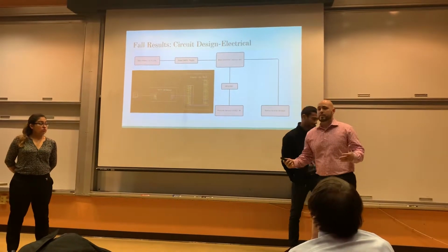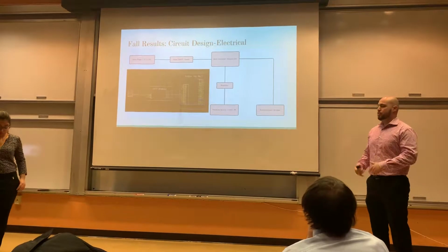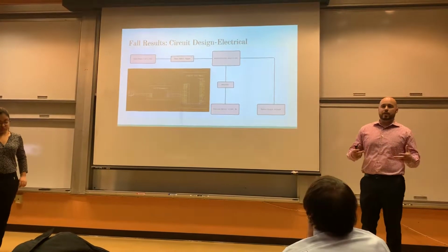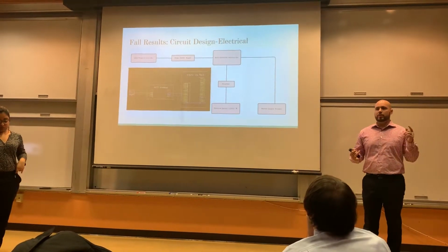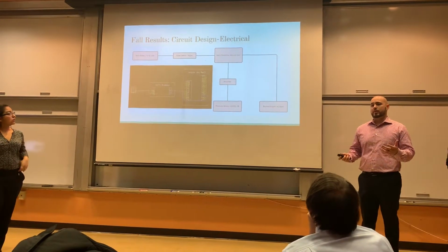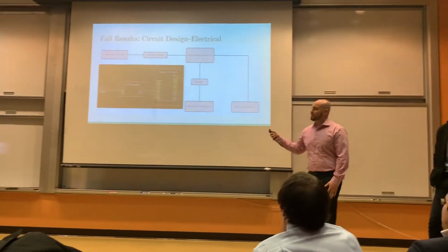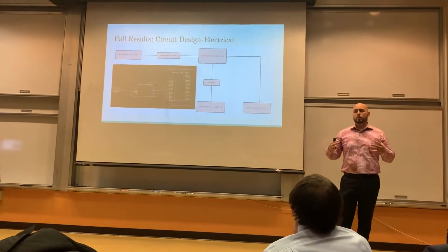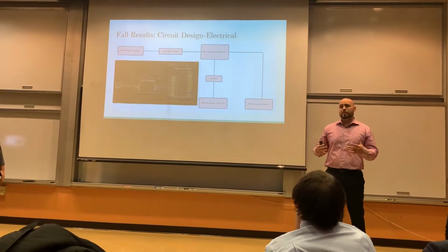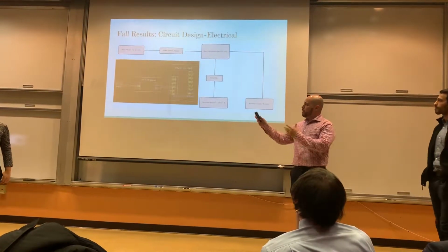All right, so yes, the second subsystem of Project RAT is going to be our electrical circuit subsystem. This is going to be the system responsible for obtaining all the data, and it'll have our sensor systems for the maximum thrust, force over time curve, and also the temperature at the nozzle. We have a block diagram outlined here in the pink boxes. That's going to give us an overall idea of the components that are going to be needed to complete the sensor system.